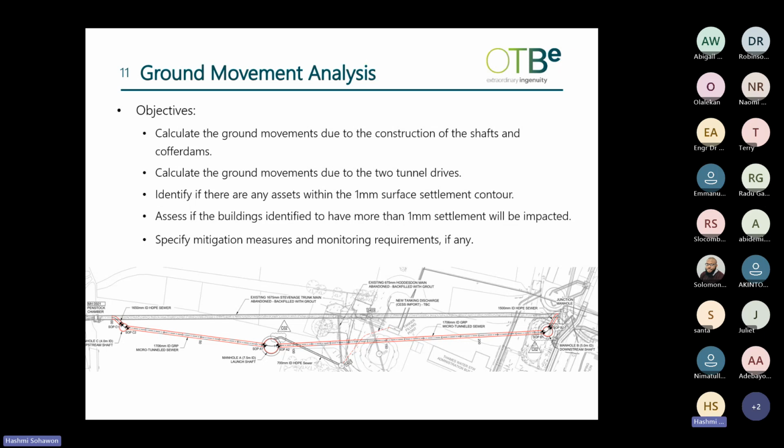We identify if there are any assets within the 1 millimeter surface contour, and we assess if the buildings identified have more than 1 millimeter settlement, whether they will be impacted. We specify mitigation measures and monitoring if required.